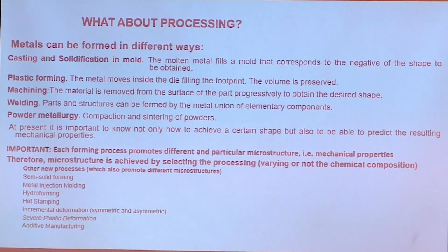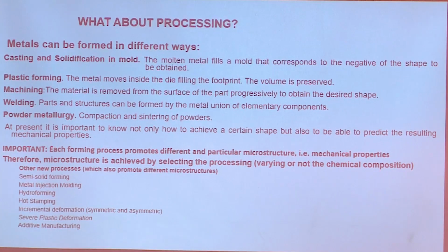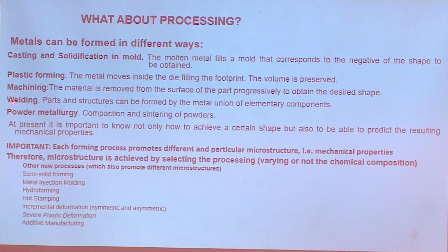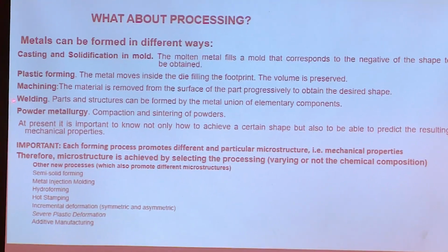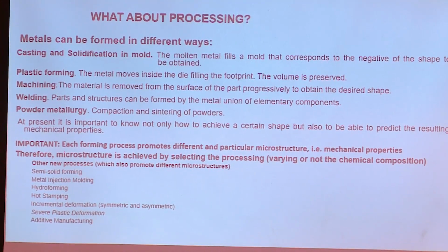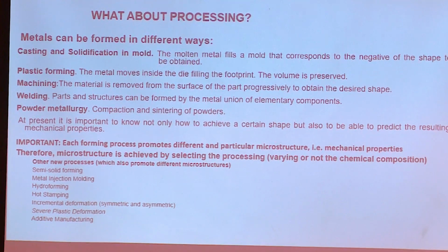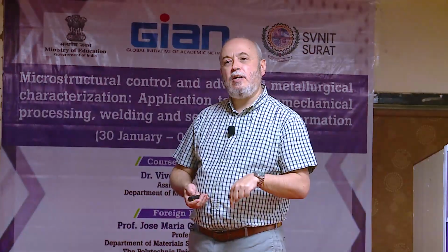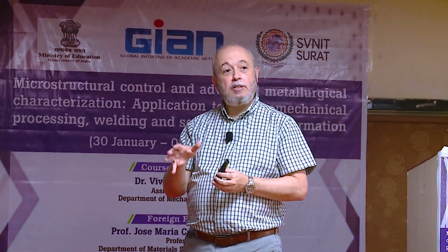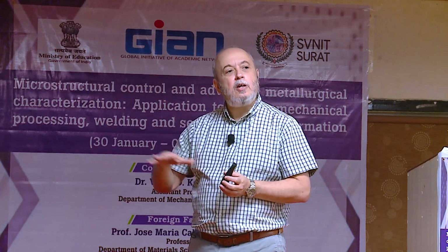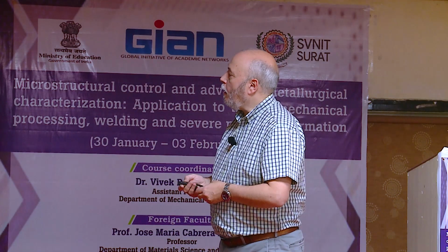welding also as a way to join metals, which is used when they are difficult to manufacture by casting or by plastic forming. Powder metallurgy, in this case your raw material must be in the form of powder, and this will be controlling the mechanical properties. Remember that when the material is coming from the sintering way, usually the mechanical properties are relatively low because the material has porosity. Also the chemical composition is not very homogeneous. So there are some drawbacks with these processing methods.